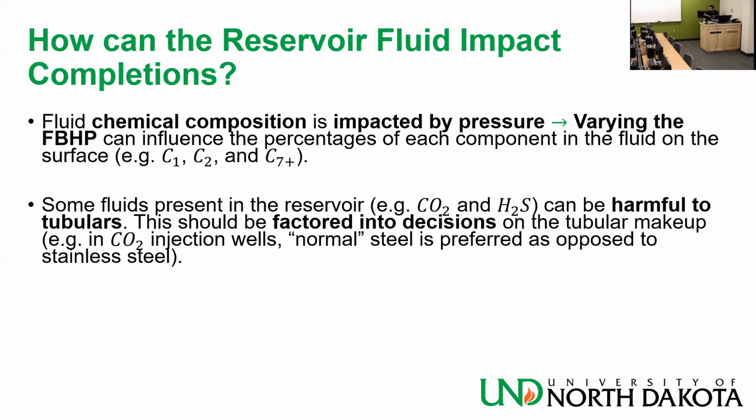Same thing for production. If you are going to be producing a lot of H2S, you need to be able to deal with it. So that's when you're going to think about a shotgun completion, so that you protect your casing. You have a tubing that you may sacrifice at some point. Corrosion from H2S is very bad. It causes what we call embrittlement. It makes everything break easier.